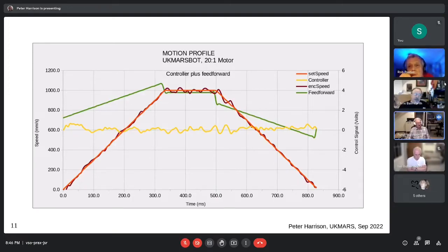All these things are true. The poor sensor resolution is largely what's responsible for these oscillations that you see. Right, because it's only doing like 3 counts per millimeter, whereas on my contest robot Decimus, I've got, I can't remember, 100 times that. So the opportunity to get the answer right is much better. The lack of precision means that there's going to be some oscillation.